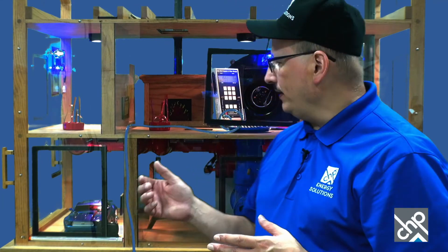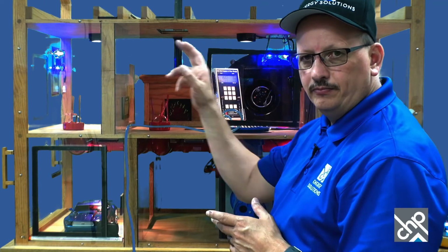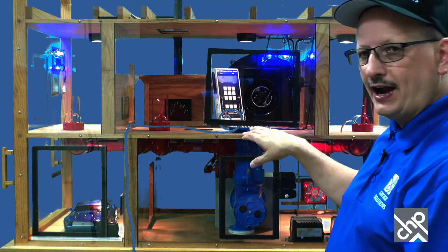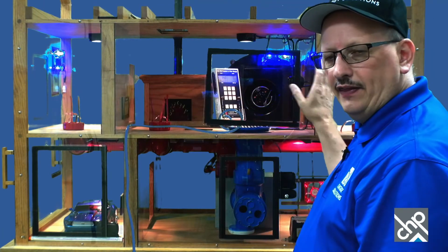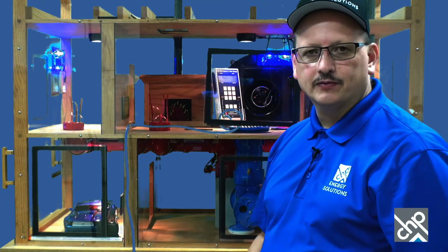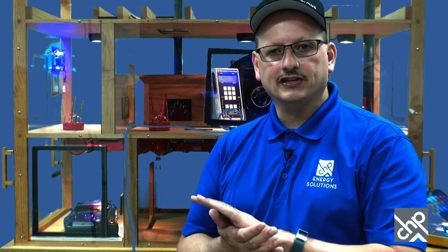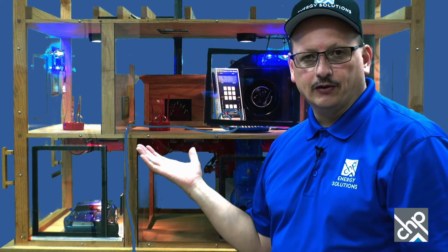And at this point, we've got all three doors closed, the bedroom, the bathroom, and the basement door. And where's your return? Your central return is right here in the middle of the house. It's looking for the air that's trapped behind this door and this door. And of course, if this door was open, it would give it more volume. So doing some pressure relief would really help in this particular scenario. And this would be your worst case.